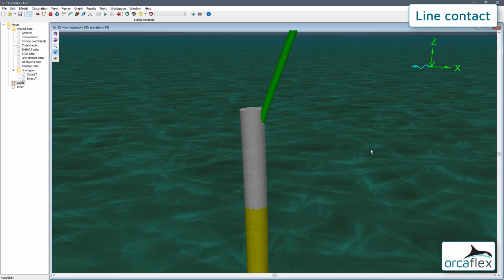One workaround for this is to just add more nodes to the penetrating line, reducing the magnitude of the breakout. However, this isn't always a desirable solution, as it may adversely affect the model in other ways.